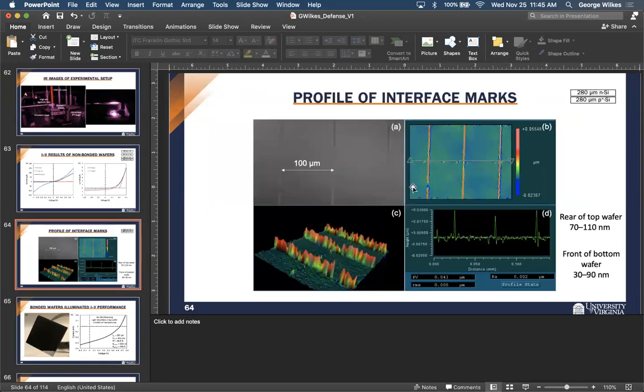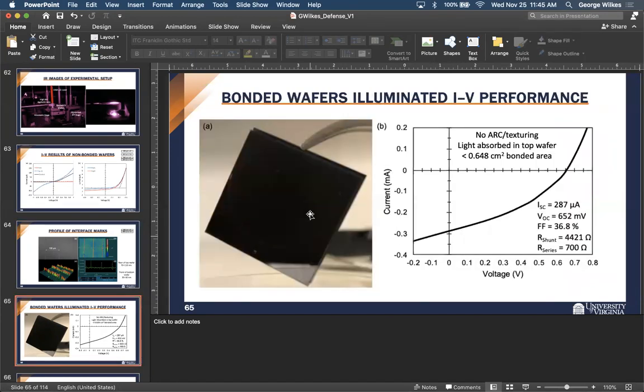No, I could have picked up some of the RMS roughness with the Zygo, but I didn't look at that. It's still bonding. I wasn't too careful with the surface. The surface was clean, but I wasn't super careful with plasma treatments or anything like that, and it still was able to bond. I did this 3 or 4 times with different samples. So you can be relatively uncareful and it'll still work, which was nice. But I'm sure I could improve it much further if I did this in the clean room with all these plasma treatments to keep the surface nice, and also looked at the bowing of the wafers.